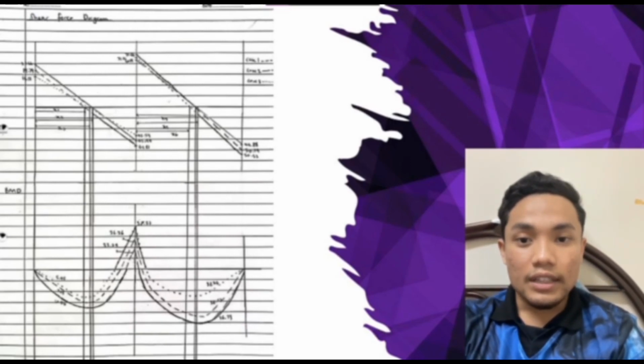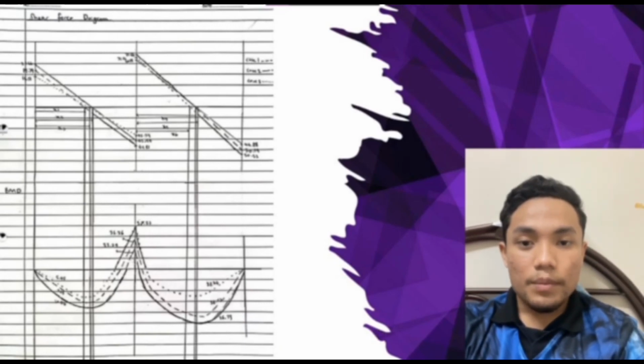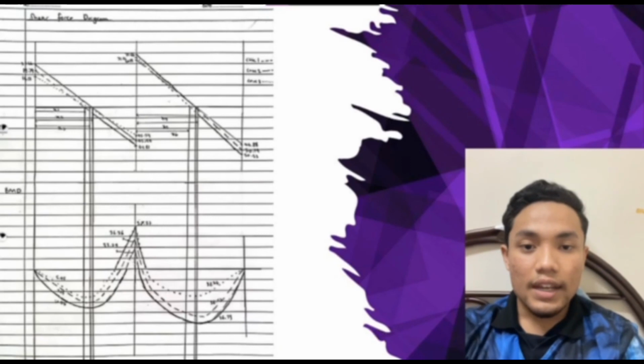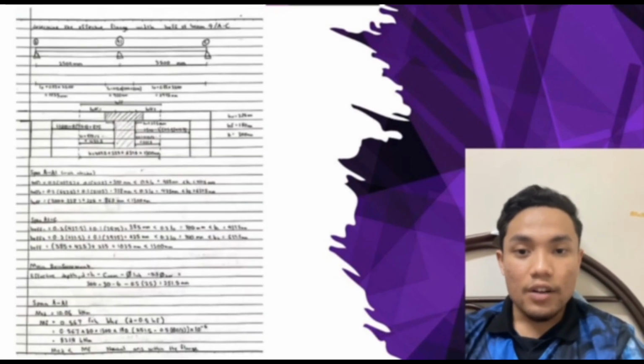In that situation, I take the maximum value for each. The shear forces are 23.66, 29.81, 71.65, 50.3, and the bending moments are 10.06, 37.53, and 36.73. After I get the design action at the beam, the area of tension reinforcement is 92.29 mm square.